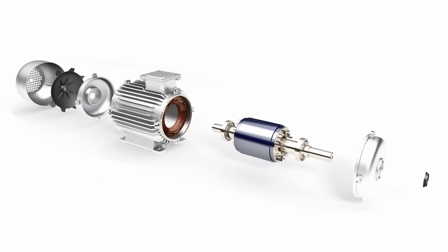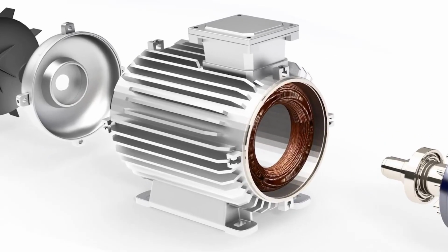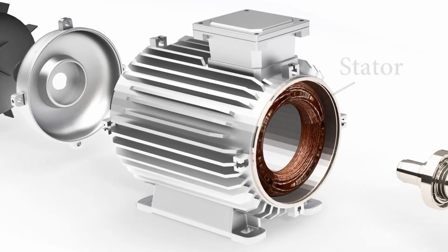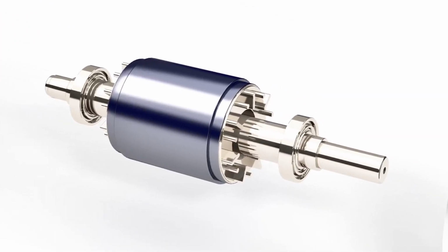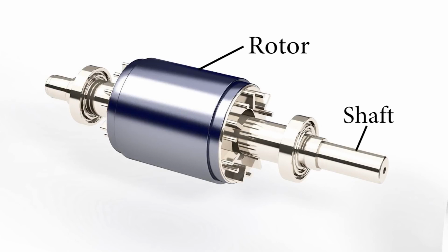The stator is the portion around the outside of the motor, made of lots of windings of thin copper wire. With a three-phase motor, there are windings that are specifically powered by the A phase, windings for the B phase, and windings for the C phase. The rotor is in the center of the motor and is the portion that spins when the motor is turned on. The rotor is also attached to the motor shaft, which connects the motor to whatever it's running.